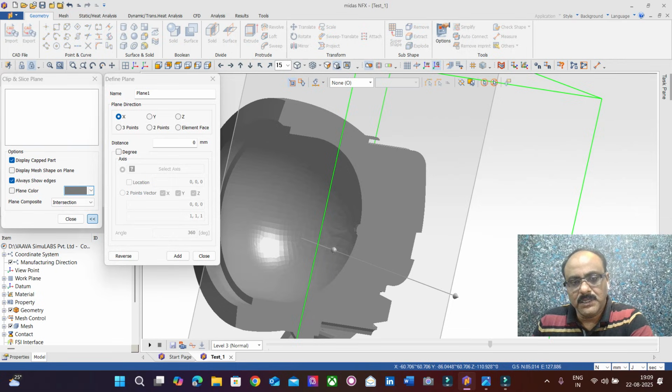Okay, so what we are doing is we are going to very carefully mesh this using hexahedron brick elements, and this is again isoparametric in nature, and these hexahedron brick elements are less stiff than the tetrahedrons or any extensions of triangular elements.